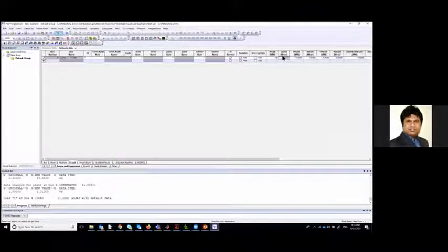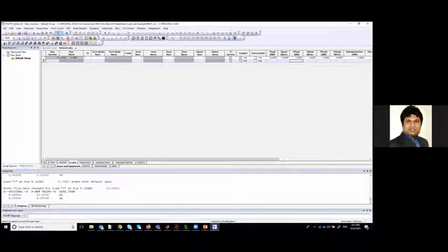and Q as 6. If it is a constant, we consider that this is a constant power load. It could be a constant current load, IP and IQ, or it could be a constant impedance load. There are three different types of load in the network. So we can put depending on the load. Here I have considered constant power load. That's why I put P and Q.